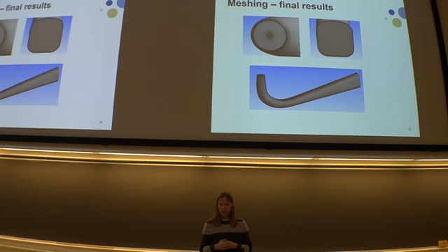The picture to the right is showing the outlet, so it's not an O-grid mesh, but my co-advisor Chirag told me that it will be okay for my simulations. And I've also used an inflation layer method at the walls of the draft tube, because that's where the boundary layer will develop, and it's important to have very fine mesh grids there.